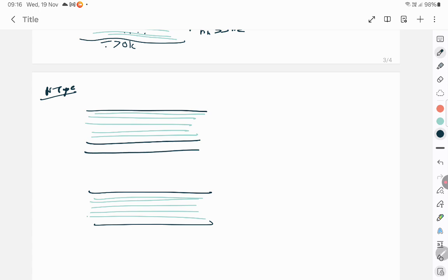So you draw the ED, which is just below the conduction band, which makes it very easy for it to conduct. 0.01 electron volt is sufficient for it to jump. And this is EV, and your ionization energy is EC minus ED. It's considerably reduced, and you know the value is 0.01 electron volt.